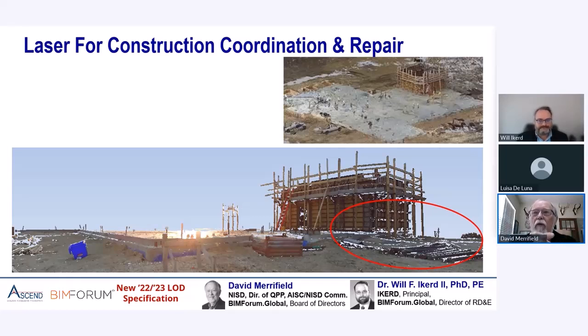So in fact, we had fabricated all the steel for this project, and it was sitting on site. And after 5 weeks of not being able to erect, the problem turned out to be that the anchor bolts were not placed within what I would say a reasonable tolerance.